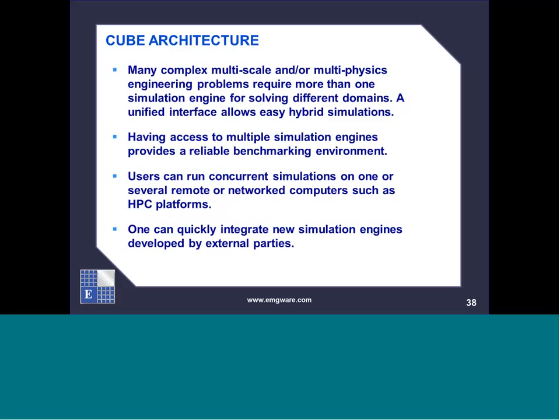Another advantage is that a lot of complex structures need to be run by different techniques in a hybrid way, especially system level problems that have different length scales. So EM.Cube provides a natural framework to use. For example, get your system set up and break it down into smaller parts. One part is wideband and goes to FDTD, one part is resonant and goes to method of moments, and so on and so forth, and that also creates convenience.